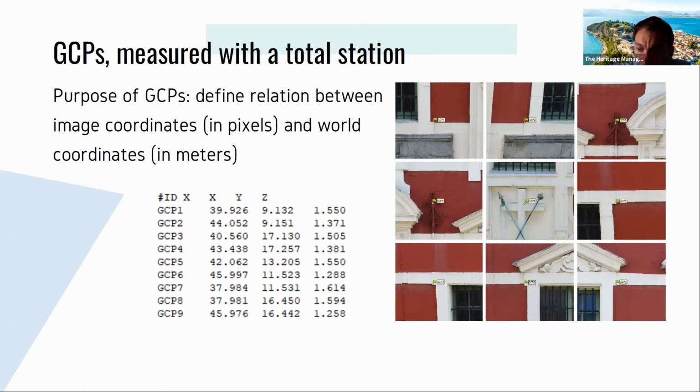work with facade modeling. Very interesting about this is that your Y-axis can be used to define your leveling of the facade itself. So for example, if you want to have the elevation or all the elevations related to the front door, to the lower part of your front door, for example, you can just set that to a value of 100 or 10 or even 0.